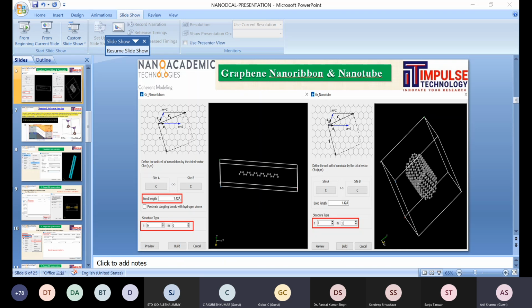Now, whenever you define certain calculation parameters in density functional theory to simulate the material, you need to set some self-consistent parameters, such as electron temperature, energy cutoff, exchange correlation functions, k-point sampling, and some contour integral parameters. So all options will be there. You can define the basic settings.